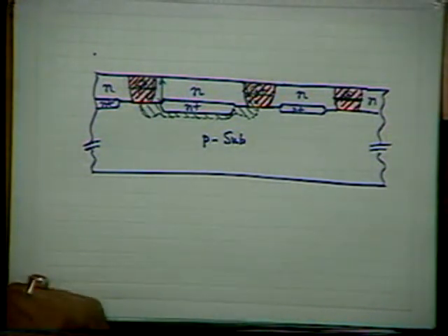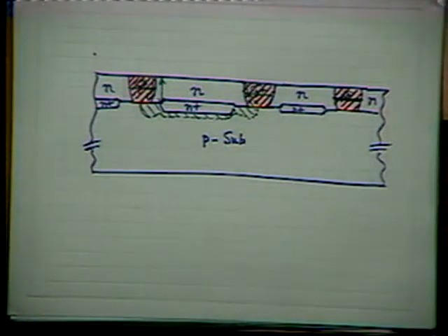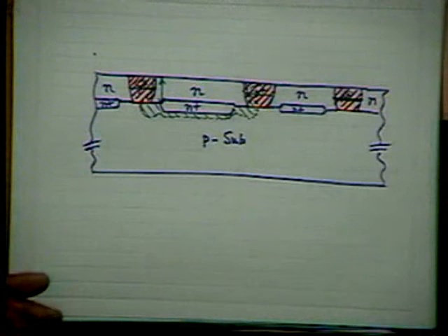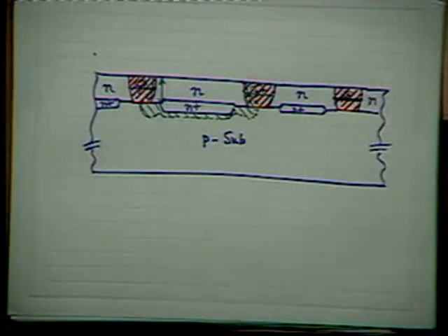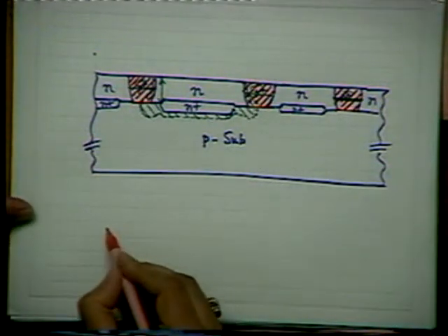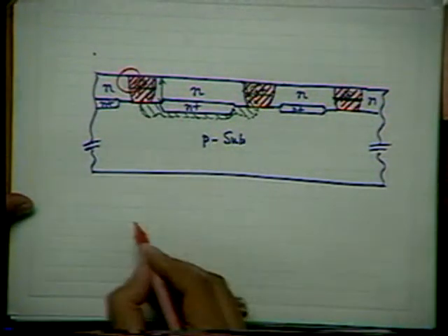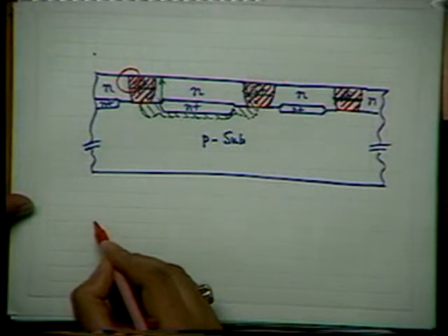Why will the silicon interface go down? Because of the volume expansion which will take place after oxidation. It is roughly twice. It will enter into the island area also. There will be a little, and that is why I'm saying that if I go into detail, I don't think we have much time in hand, but I'm trying to show what will happen at the end of a typical step. It will look like this.